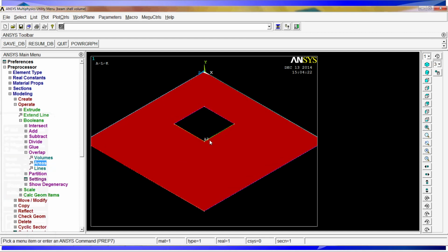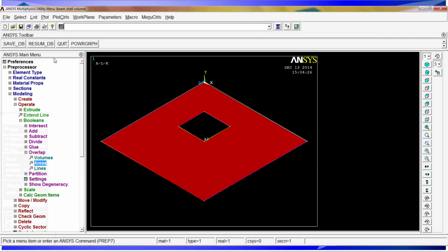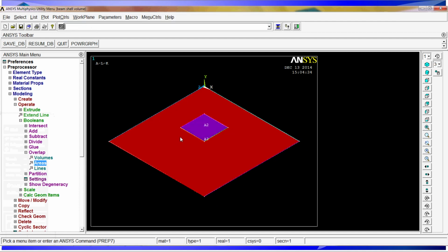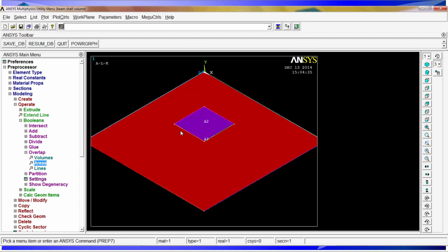And you'll see that this area now is like a table with little holes on it. To select all, we can go here and type ALLSEL, all from all select. It's going to select all the entities again. You can see everything the same way it was.